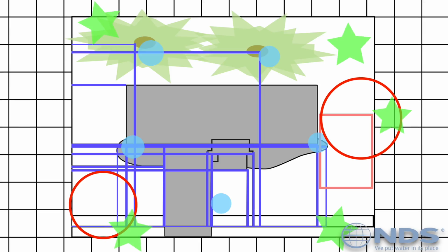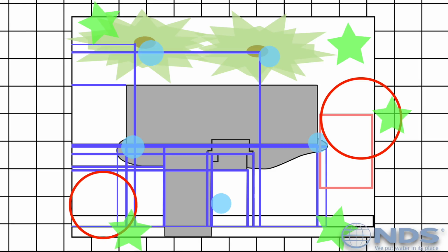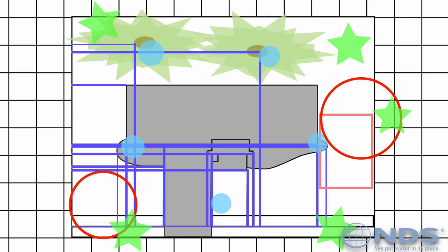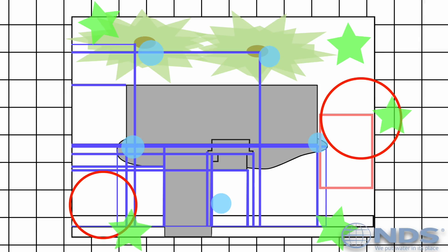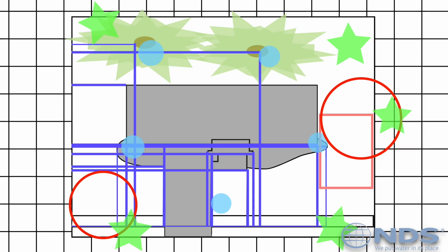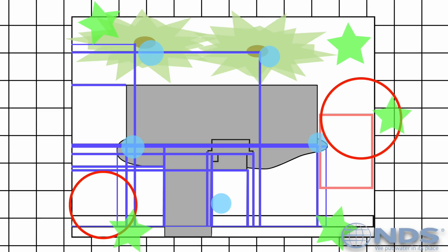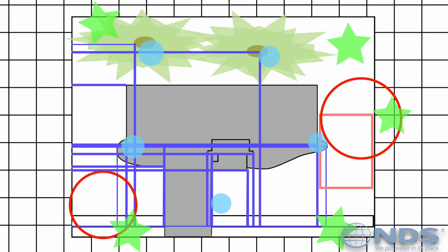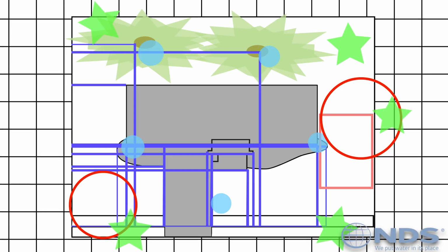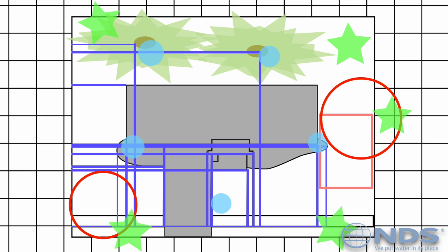Finally, identify all discharge points or potential discharge points on the plan and relate these to the areas that could drain to that point. For instance, the front yard may drain to the street while the backyard may drain to a ravine or swale. If there is no obvious discharge point for an area, note that this can be resolved with a variety of solutions that we will discuss later. Once your scale plan has been made with all of this information, you are ready to design the drainage system.